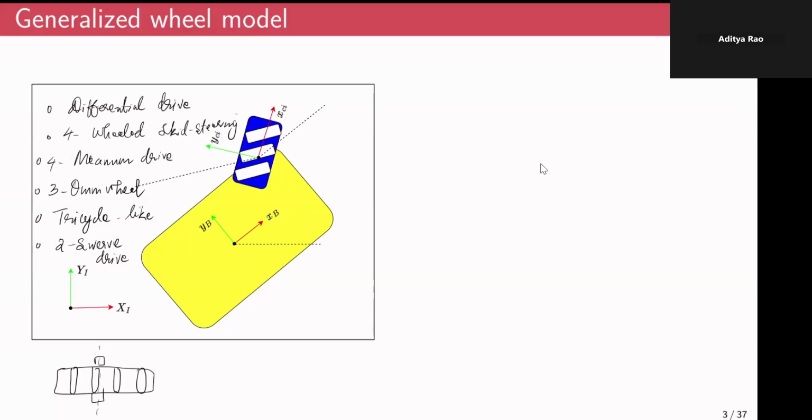So these wheels, their axis is like this. It's orthogonal to the main hub axis. So these passive rollers would enable a wheel to have the capability to slide in the lateral direction, right? It won't offer any sort of resistance. So these sort of wheels would give a mobile robot an even higher degree of maneuverability, right? So that it can basically move in a lateral direction without changing its orientation.